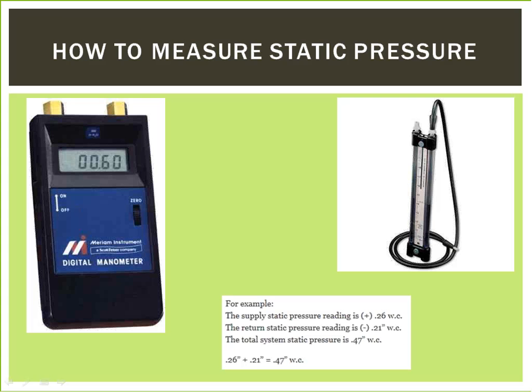Step 6. Calculate the system's total external static pressure by adding the two values. Since the negative and positive signs identify the type of pressure measured, you can ignore them when adding the two values together. An example is provided on the screen for your review.